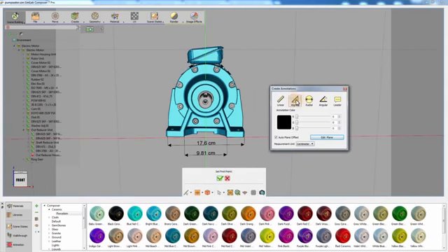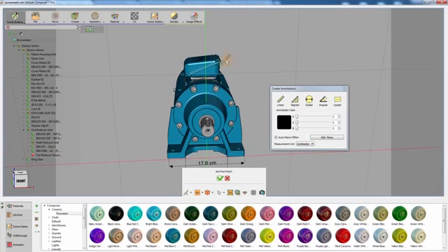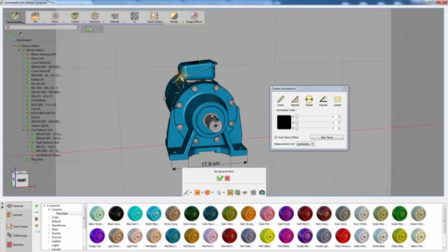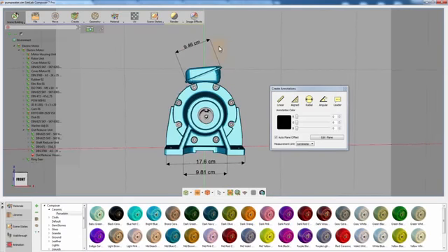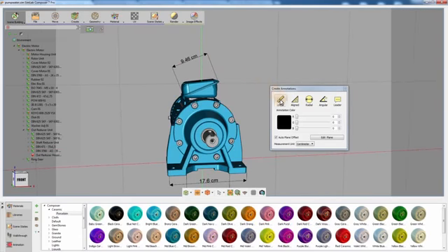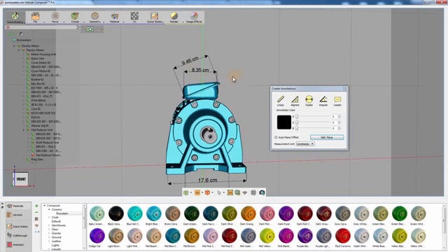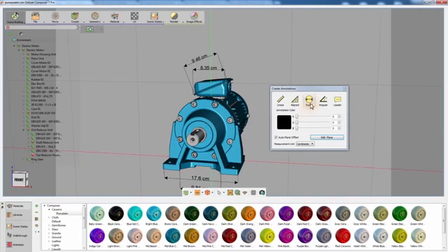Click on the Align Dimension tool and measure the width of the electric box. Now measure the electric box's width using the Linear Dimension tool. The Align Dimension tool will measure the distance between 2 points without projecting the values to the principal axis, which can be useful in measuring diagonal surfaces and edges.